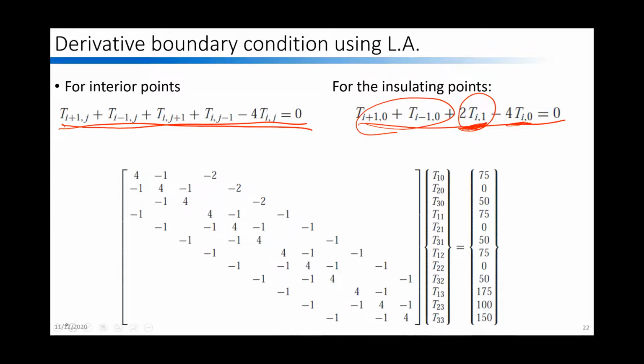We're going to look left and right, but now we need to look, say, up and down as well. We're still going to then write out that equation for each individual point, apply the appropriate boundary conditions, which may require writing out an additional equation that needs to be considered, and then solving that set of equations using either linear algebra if we have a linear solution, or something like Gauss-Seidel if we need to take nonlinearities into account.